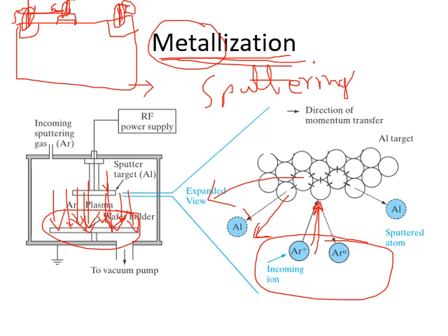But nowadays they are preferring copper also, not just aluminum, right? Because of some minor changes in electrical properties, copper can also be deposited, but copper cannot be deposited with the sputtering technique. This technique is not valid for copper.